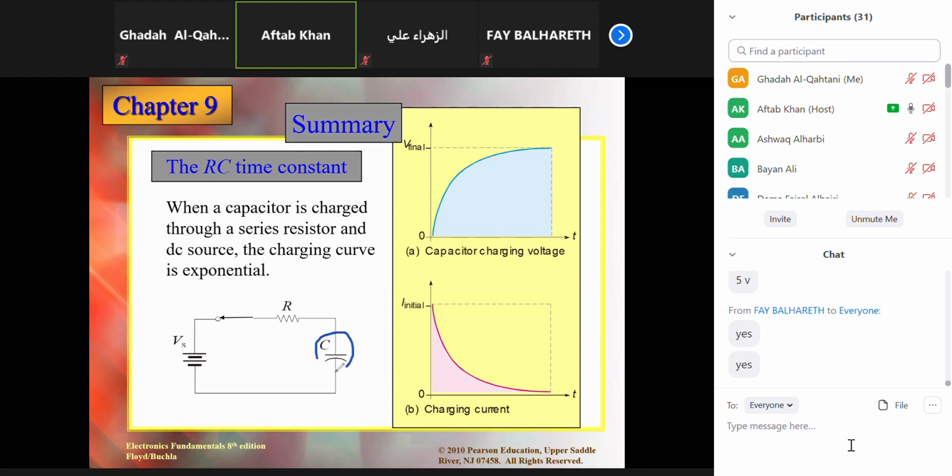Okay, so it is just a concept, as I told you. While it is charging, it keeps allowing the flow of current through it, and when the current is passing through the capacitor, the voltage across it keeps building exponentially. All right, and the current keeps decreasing exponentially. Fully charged, that is, current fully 0. No current will flow at all once the capacitor is fully charged.